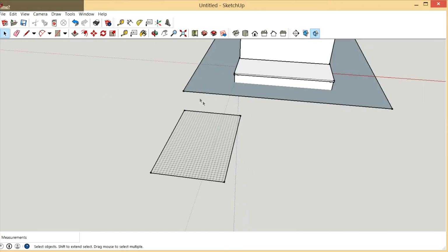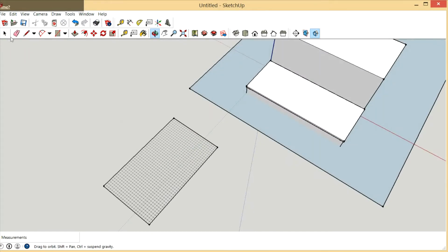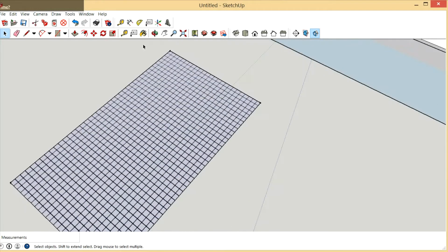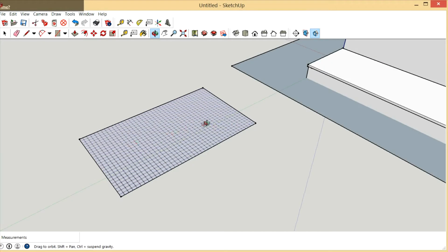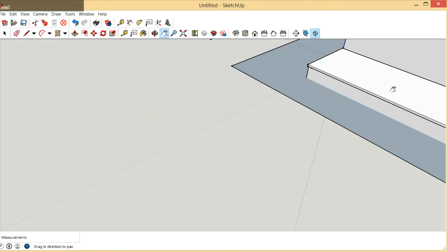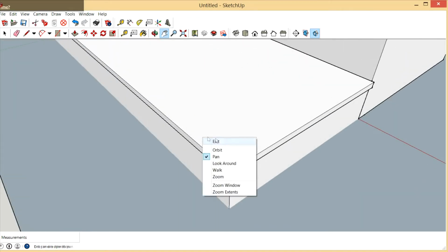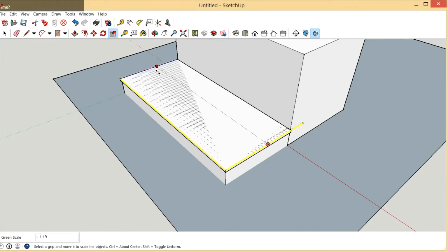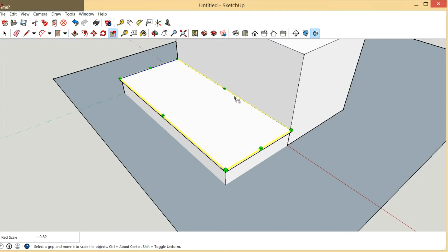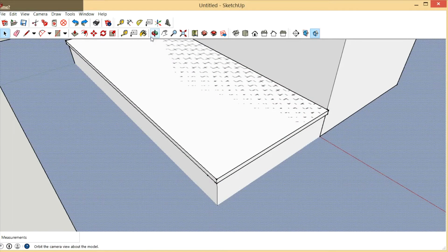So what we would do here is these sheets of welded wire come, I think they're 6 feet wide and 15 or 20 feet long, but we'll just pretend we're going to put it in our slab here. We're going to scale it. We're just going to take it and move it out to there, and then over here somewhere, there it is. The welded wire, you don't want it to be out to the edge. You actually want it to be at least 3 inches away.